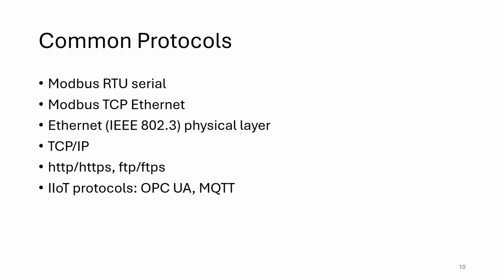These days that's replaced by Modbus TCP, which is Ethernet based. And Modbus is a sort of standard, or de facto standard, protocol that's adopted by many different devices. It's not completely standardized, but it's close enough that normally two Modbus devices would be able to talk to each other, and it's also quite easy to convert from Modbus RTU on serial to Ethernet and vice versa. So this allows a lot of interoperability between current and legacy industrial devices.